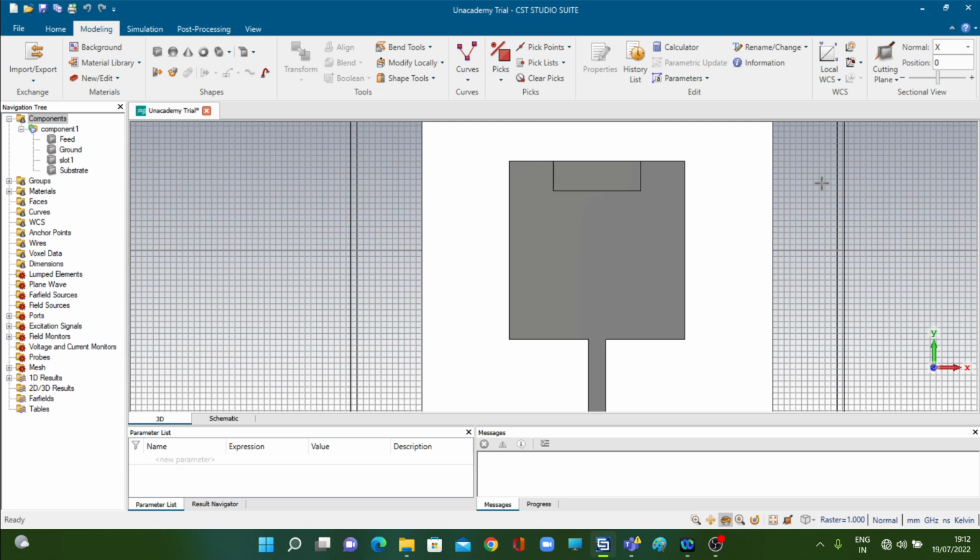The problem is, if you want to enhance the bandwidth progressively, continuously, from the knowledge that we have developed till now, it seems that we have to increase the path length. How can we increase the path length? By increasing the dimensions of the antenna. Now see, we can't increase the dimensions of the antenna indefinitely, because our first design motive was to prepare a compact structure.